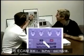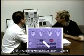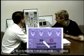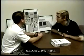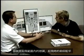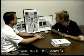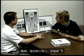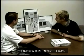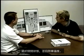On the ECAM panel, we have a takeoff config. What are you doing when selecting the takeoff config? I'm simulating that the thrust levers are applying takeoff power in order to test that all the configuration parameters are met. What are some of those configuration parameters that are checked? That would be the flaps in the takeoff range, the pitch trim in the takeoff range, the spoilers are armed, and the rudder trim on the later A320s and on all the 319s. We also check for the side stick fault by takeover, the doors not being closed, and the brake temps.